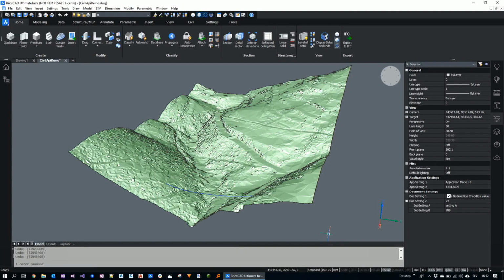With the API, you can do some specific functionality related to local standards or even companies, or you can automate some tasks. With this simple example, it will automate the tasks, so it will create an accumulation, join the surfaces, and create a water surface at the end.